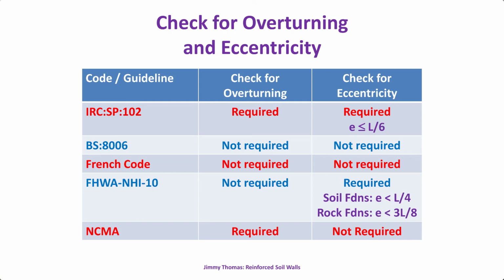Now, the only slight problem we have is with IRC. This L by 6 was from the old days, which was not a limit state method. That means the load is not with the load factor, it is the actual working stress load, and that was okay. But if you look at FHWA, which is a limit state or LRFD design, here the loads are factored. So there, e is less than L by 4. So now,